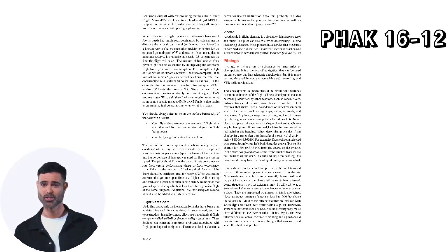You should always plan to be on the surface before any of the following occur. Your flight time exceeds the amount of flight time you calculated for the consumption of your pre-flight fuel amount. Your fuel gauge indicates low fuel level. The rate of fuel consumption depends on many factors: condition of the engine, propeller or rotor pitch, propeller or rotor revolutions per minute (RPM), richness of the mixture, and the percentage of horsepower used for flight at cruising speed. The pilot should know the approximate consumption rate from cruise performance charts or from experience.